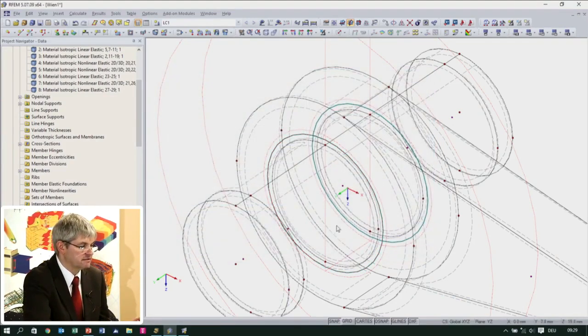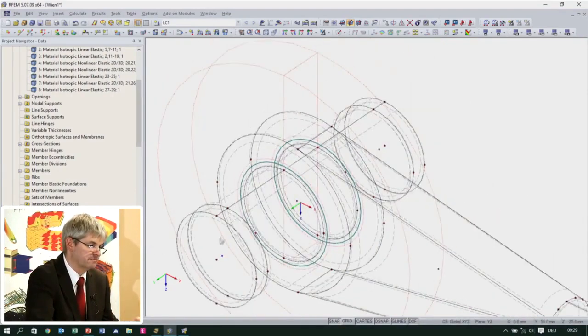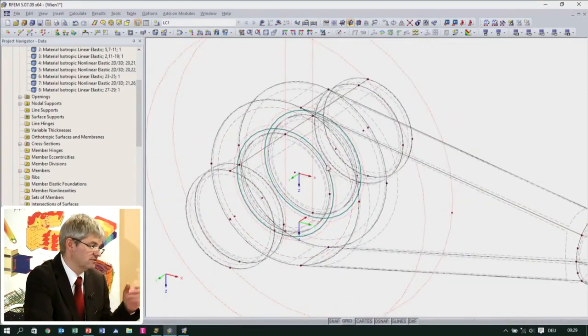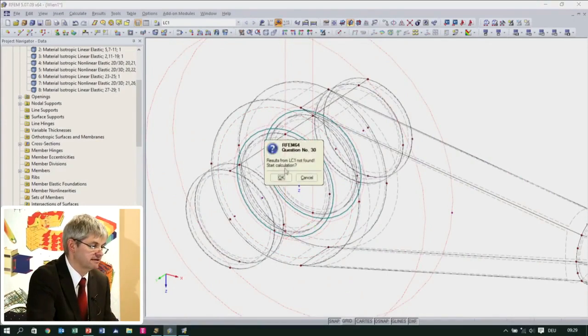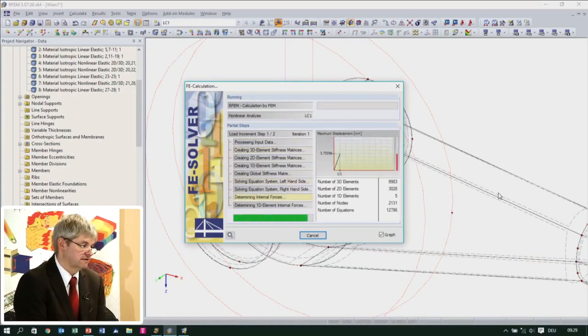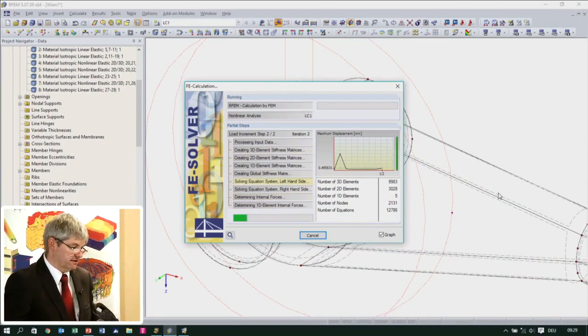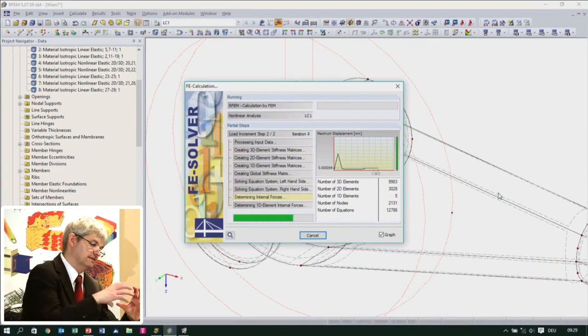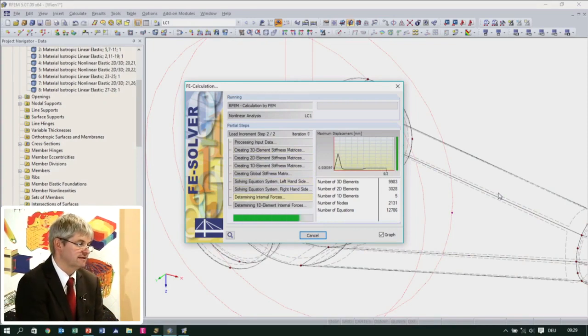Okay. So now the bolt and the eye are established with that contact condition, and I can run the analysis again, and it will have this delaminating effect. Also, you can do things like slip. So if there's a little bit of slip, then everything changes. You can look at all the results in depth. It's not a black box solution.